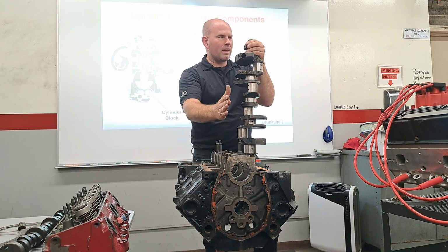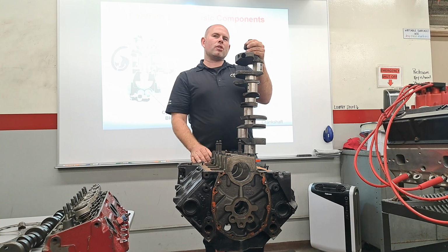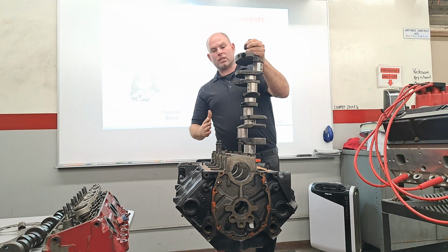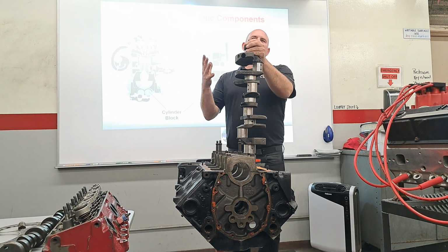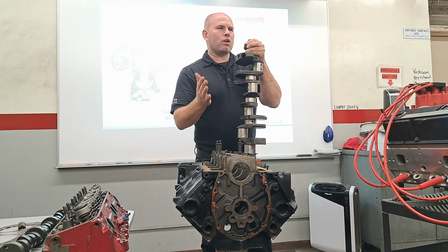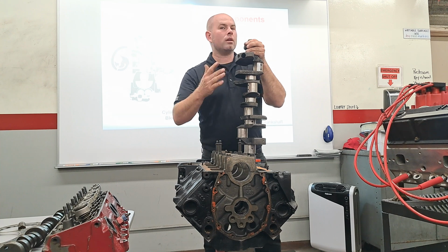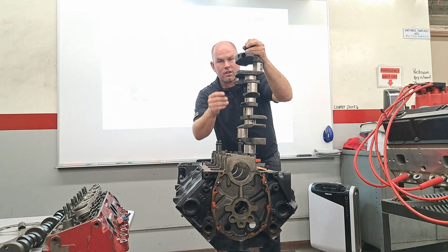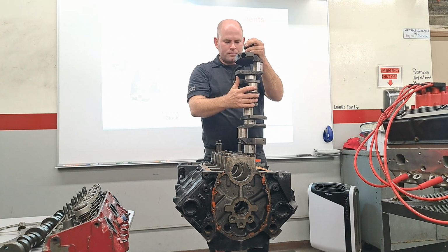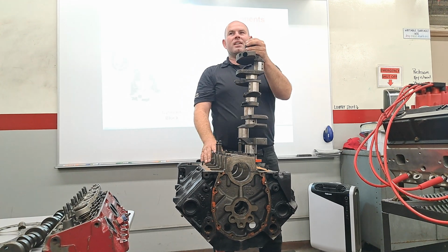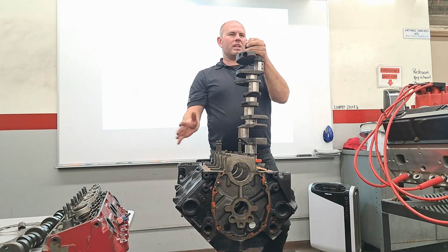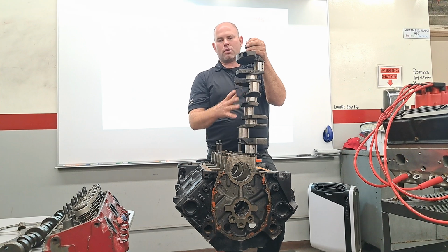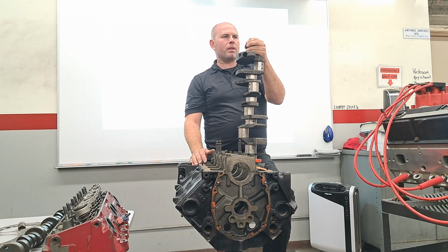Now, I mentioned something earlier called line boring. If you had a block and you had a problem with those mains, you could actually send it to a line bore, which, picture, it's not exactly accurate, but picture a giant drill bit. And the giant drill bit has to line bore all of those together, and that'll get them all in line. Now, the thing is, from the factory they do that, right? But let's just say you're doing all sorts of crazy horsepower and you make a lot of torque on the crankshaft, it could potentially twist the block.